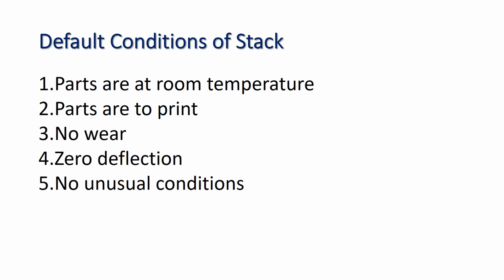And what are the default conditions of stacks? We should understand this because we are calculating stacks by assuming that all the parts are at room temperature and parts are to the print, because we are using drawings. No wear and tear in the part, zero deflection, no unusual conditions present in the part drawings or 3D models.